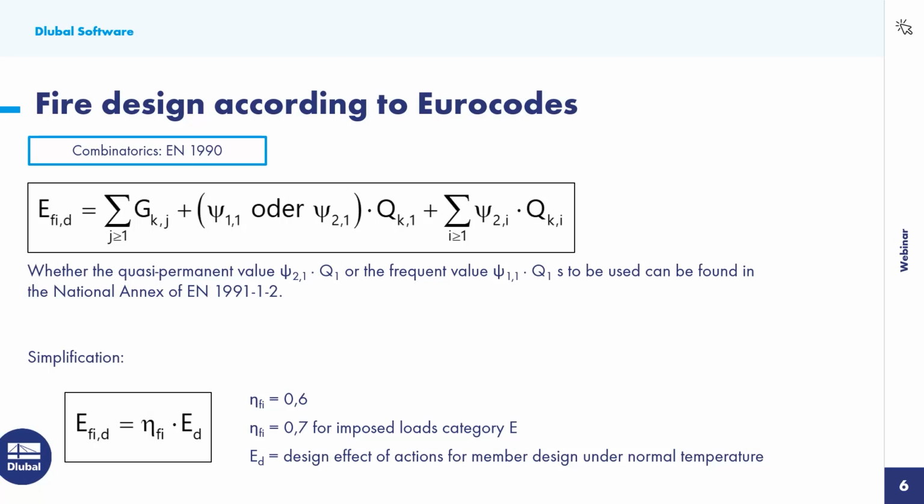As a safe side assumption, the loads from the code design multiplied by a reduction coefficient can also be used. However, this is generally uneconomical and therefore not recommended, especially when we use a design software that can do the correct combinations anyway, like RFEM.